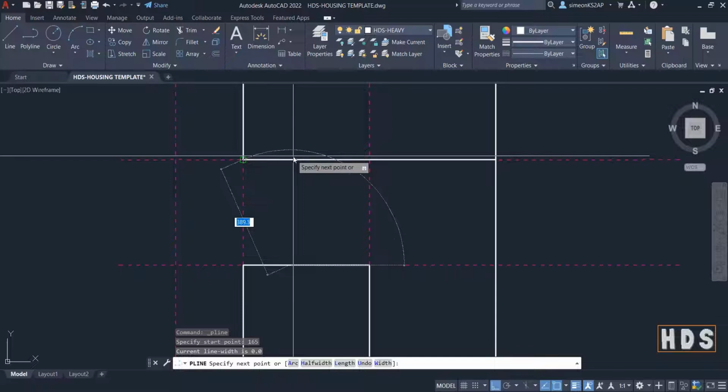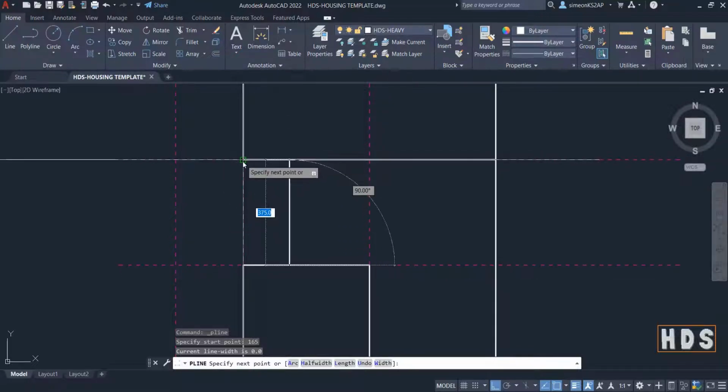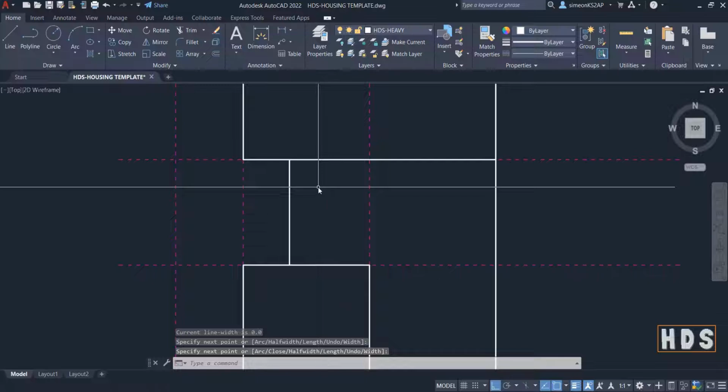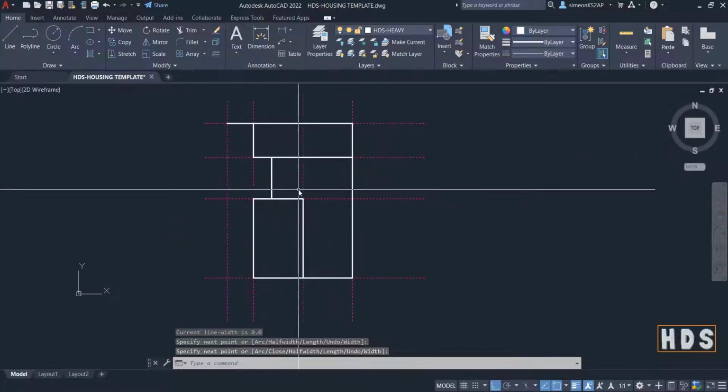Now I will extend that line, and to snap to that particular point, I will snap to this corner and then go along that line. You will see that cross sign. That means that it is perpendicular to that particular point. Now when I see that particular point, I click and I know our lines are meeting in that particular point.